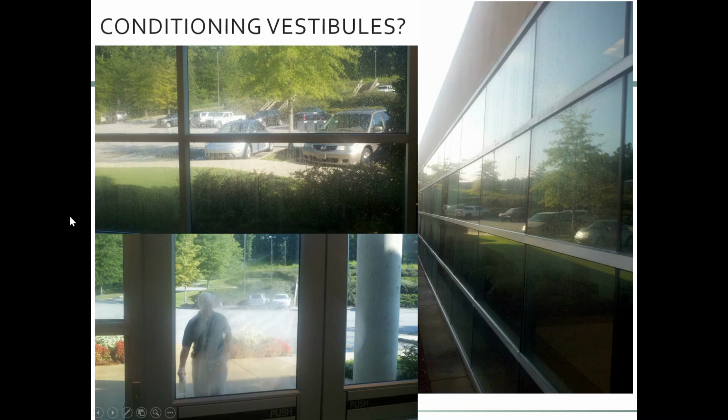Okay, and you'll get a kick out of this, Joe. This is a commercial building we visited in the summertime, and let me just say it was not raining, but they were over-conditioning their vestibule, so much that the glass was below dew point, and it looked like the building was sweating on the outside, because it was. That wasn't rain. So don't do that. That's a waste of energy.